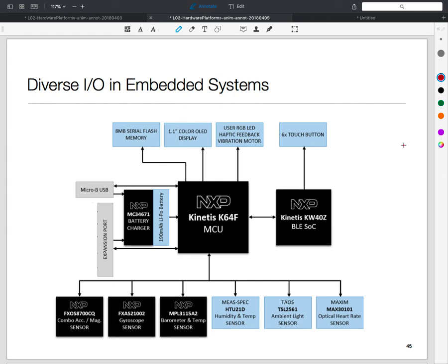Three. Three will get me the center of gravity, and then I could be anywhere. So 6: x, y, z, roll, pitch, yaw. By taking gyro, magnetometer, and accelerometer together, you can actually figure all of them out.